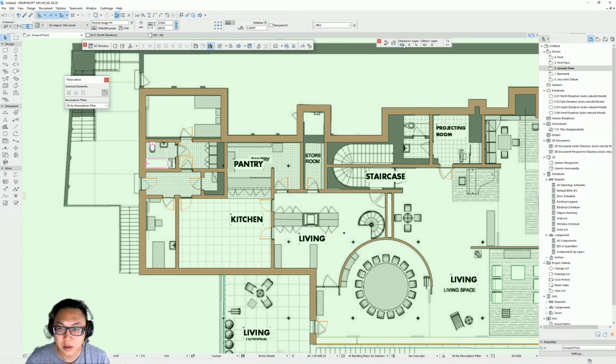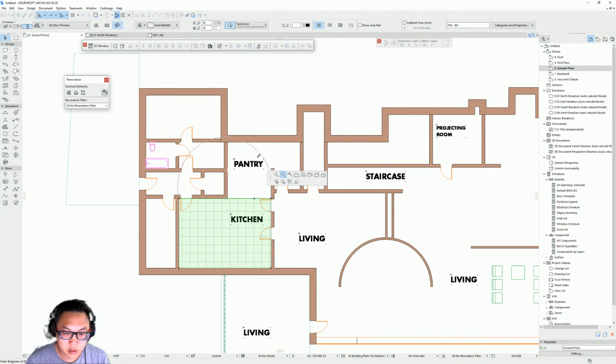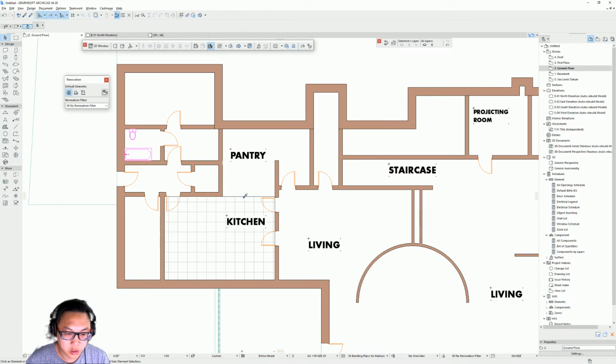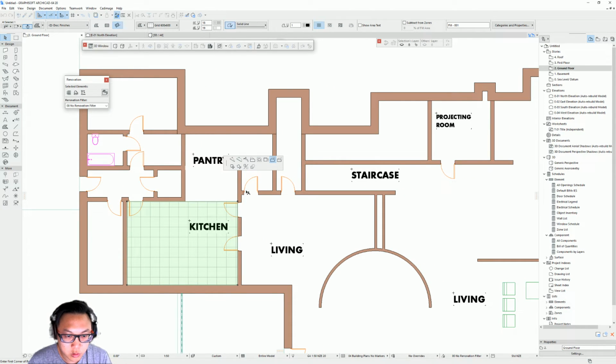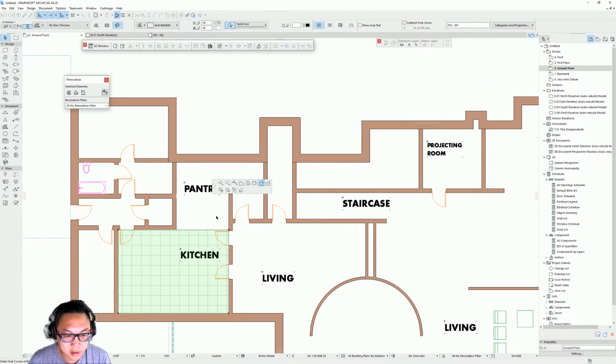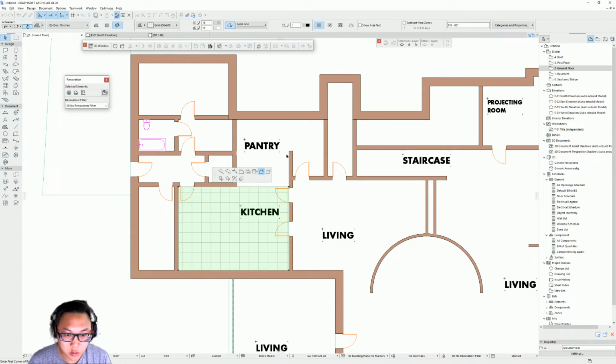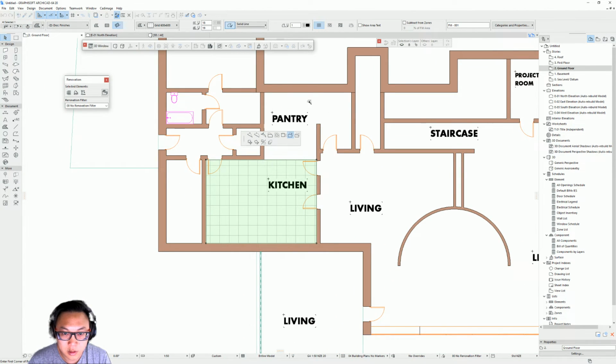Like that. So now you need to have tiles on this side. So you could either do that again slowly, but then it takes time. So one way of doing it is you just select the original one that you had, go into the edge and add polygon, and we can use the magic wand tool to let Archicad just do the work for us. So press the magic wand tool, click in the center of the space, and ta-da!